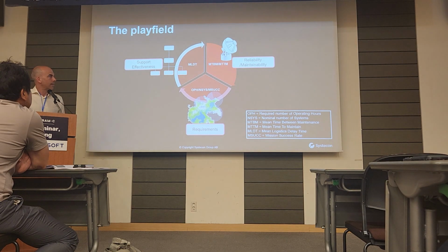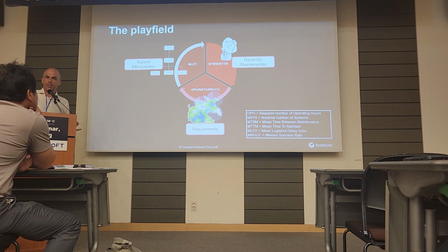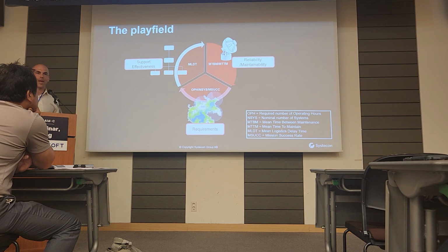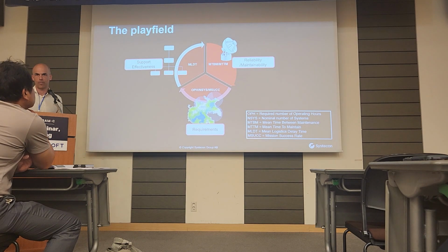Because mean time to maintain is the value given that you have all the things you need to do the maintenance. You can never fix the system faster than MTTM, regardless of how many resources or spare parts you have. But the challenge here is how long you have to wait for the correct spare part, for the resource, for the administrative work, for clearance of material, etc. This will determine the total downtime of the system.